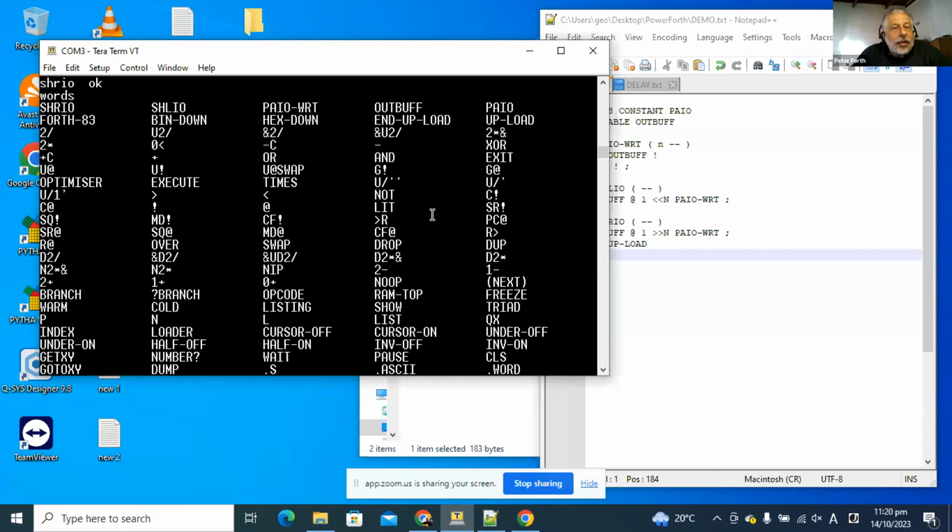Andrew, on the data sheet of these chips, these are all descendants of the Novix. We were talking about this before, but the RTX has more power than the Novix and was able to execute bursts of up to 15 MIPS, explained on the data sheet with the 10 megahertz clock. Right. So this means that it was able to execute up to approximately 4 to 5 instructions in a clock cycle.